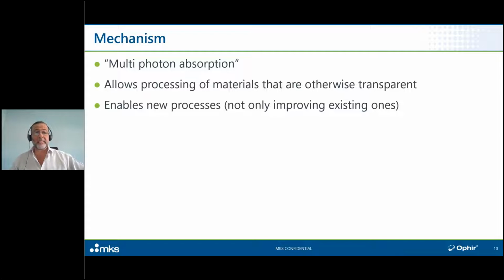And besides improving existing processes, it enables the development of some pretty nifty new processes. Here's an interesting application I came across a while ago, certain types of marking of syringes, medical industry. They use ultra short pulses which change the refractive index of the glass to give the visual appearance of printed material, printed symbols. Regular short pulses, even nanosecond pulses, would create micro cracks in the glass, but will not do the delicate work of changing the refractive index without affecting the surrounding glass. That was one hyphenated word.